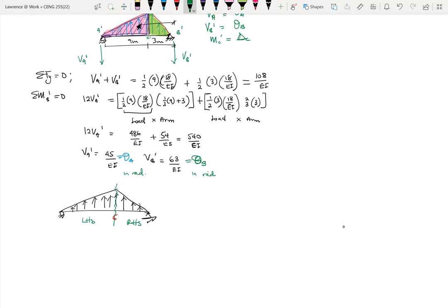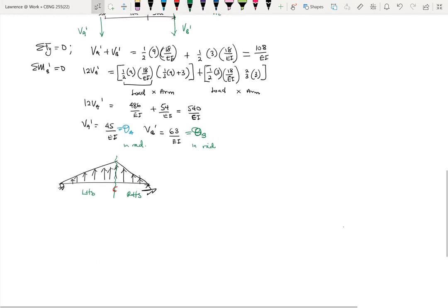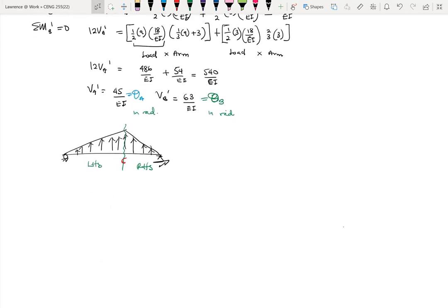Whichever one you would want to use for your calculations is fine. And then we know that anytime you cut a section at any point along the beam, you would introduce three unknowns, right? Per the three equilibrium equations. So we have a moment, a shear, and then a horizontal or axial force. Okay. So let's deal with the left-hand side. So with our left-hand side, we have this behavior.